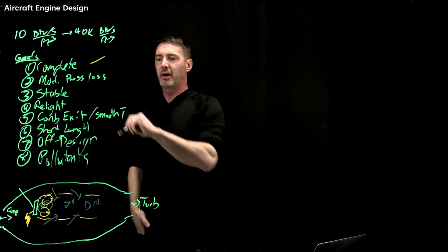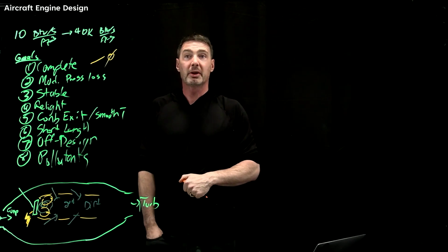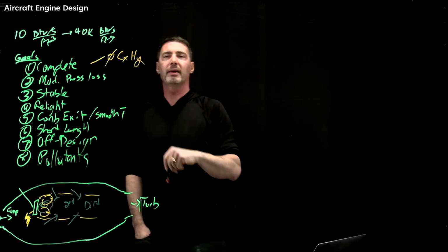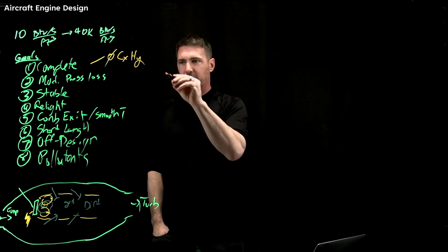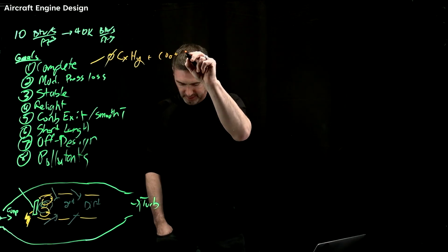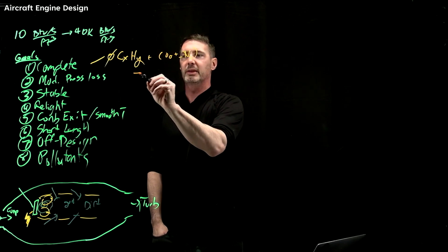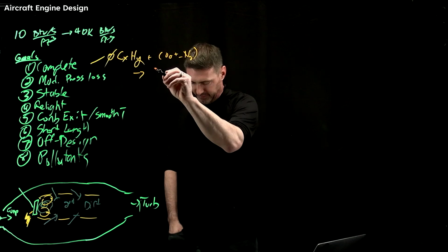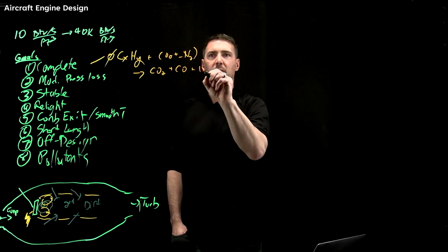So I'll actually sort of draw it up here. Again, you have your stoichiometric ratio, and so you've got some sort of hydrocarbon, CxHy, if you were going to do the full version. It depends on what x and y are. And of course, we're adding air. Yes, this is O2, but it's also that fraction of nitrogen, okay? And then that's going to turn into all the standard things: CO2, but also CO and water.